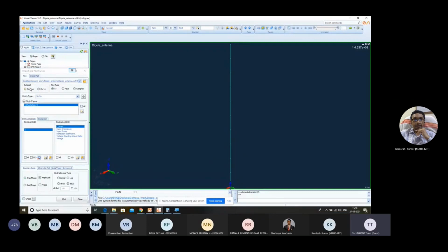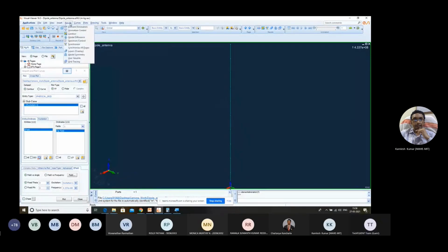So here we have contour and we have curve. Under contour, we have node and spherical grid. If I select spherical grid, I can go ahead with far field, the different reports. You can see n number of frequencies we have, only one excitation will be available. So we can go ahead with the 2D results as well. Let us just get started with the 3D result first. So let us just select this contour. So we have got the contour part.